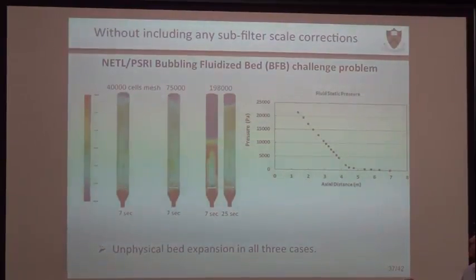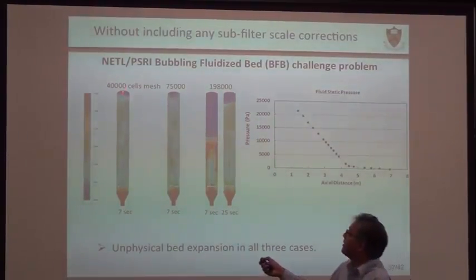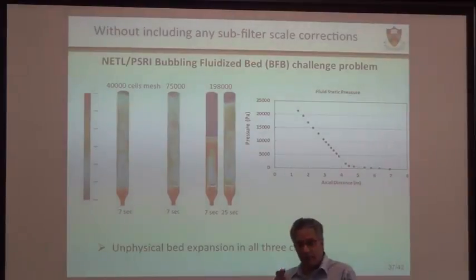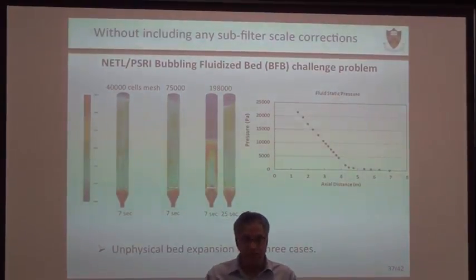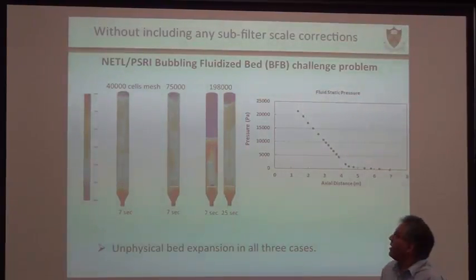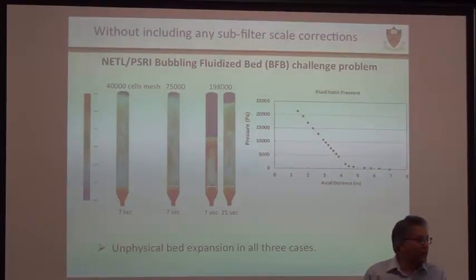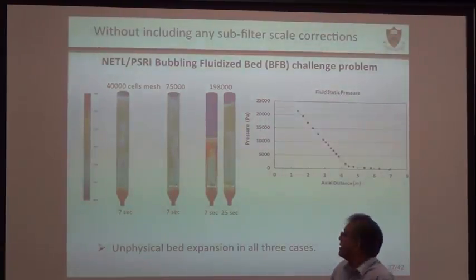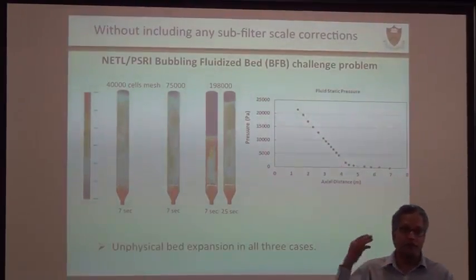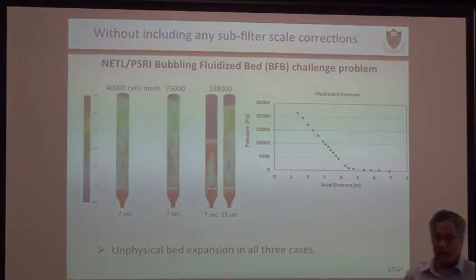If you take those models that I wrote, saying that we know exactly what this fine-scale data results are, and if I try to simulate them with finer and finer grids, by the time I put 200,000 grids, that's a large number for two-phase flow because the number of variables is much larger than in single-phase flow, you find that these simulations are already taking a very long time. It takes a while for it to develop, but eventually you blow the particles out of there. You are not going to be able to keep them. So even 200,000 is not enough. You need to go to a much finer number of grids if you want to solve the problem without doing any coarse-graining.